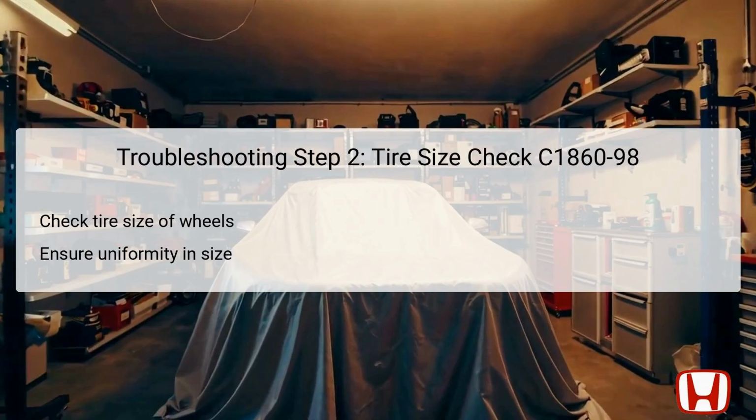The next step in the troubleshooting process involves ensuring that all four tires are of the same size. This is a critical factor because discrepancies in tire size can adversely affect the operation of the all-wheel drive system. Using the HDS, confirm the tire sizes on all wheels and compare them against the manufacturer's specifications.